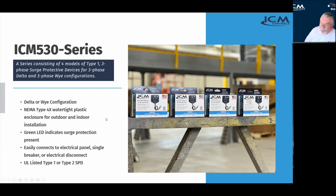They're NEMA 4 watertight plastic enclosure, welded plastic, fully waterproof, and suitable for indoor or outdoor applications. There's an indicator light to tell you if the device is still offering protection, and very easy to connect. These are a type 1 or a type 2 device. Type 1 is approved for whole home or whole panel protection. A type 2 is not.